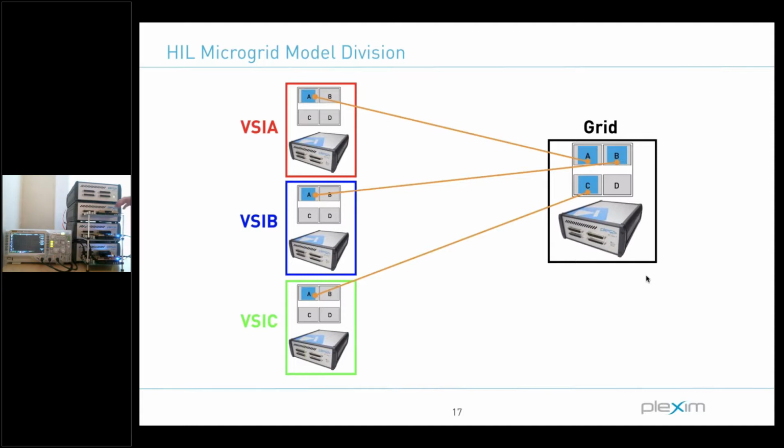One is actually a hand-coded controller, and then these two controllers, B and C, we're actually using our code generation tool. And then they're connected to the RT box with a launchpad interface board. It just maps the PWM signals to digital inputs and the analog outputs to the ADC to the converter. And then there's a few other little benefits, like there are some BNC connectors and switches that we'll be adjusting today. There's also a scope on the left-hand side, with a few measurable signals that we'll look at once the model's up and running.